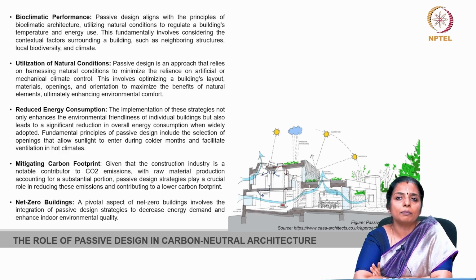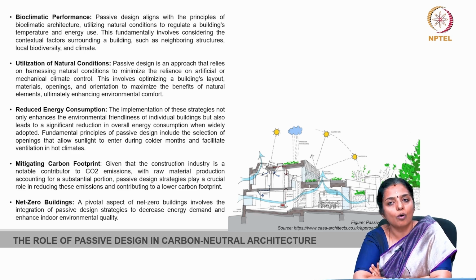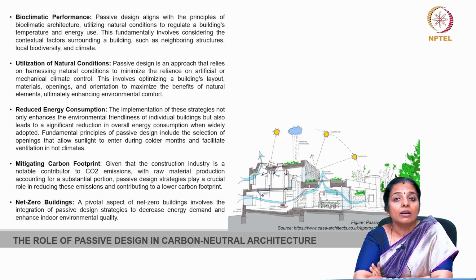Fundamental principles of passive design include the selection of openings that allow sunlight to enter during colder months and facilitate ventilation during the warmer months. It also entails mitigating carbon footprint, given that the construction industry is a notable contributor to carbon dioxide emissions, with raw material production accounting for a substantial portion.